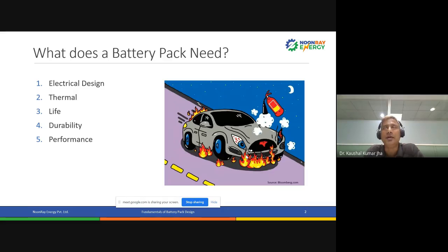Now, in the case of hybrid vehicles, what is required is high power coming in as charging during braking, and then very high power to boost up. In both cases, we have to design a battery which can give high power on demand and can take high power during braking. So how efficient that is, how well performing, that becomes performance. Safety.